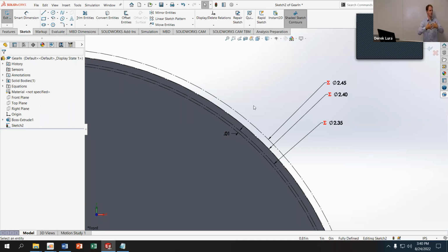Or if they're not deep enough, if they're really fat, you're going to have a very small contact area because that tooth is so shallow, right? So there's reasons, but they're somewhat arbitrary. And you could optimize those to figure out what the appropriate size is. The hard thing there is that if you start varying that significantly, you need to make sure that that variance is consistent across all of your gears. So you have to pick something that's going to work for a small gear and a big gear. And we'll see how that becomes a problem, especially with this Flintstone gear meshing here pretty soon.